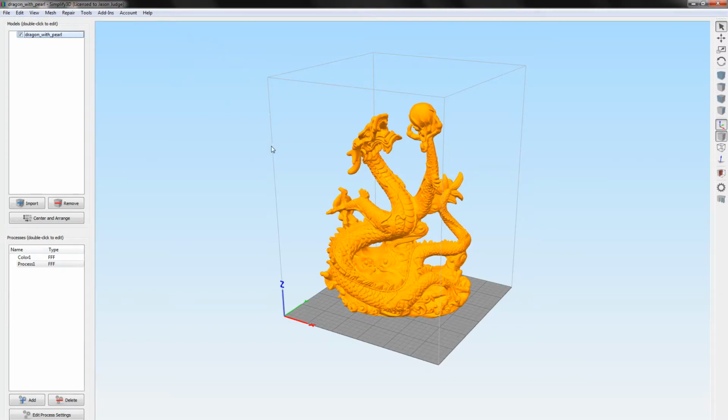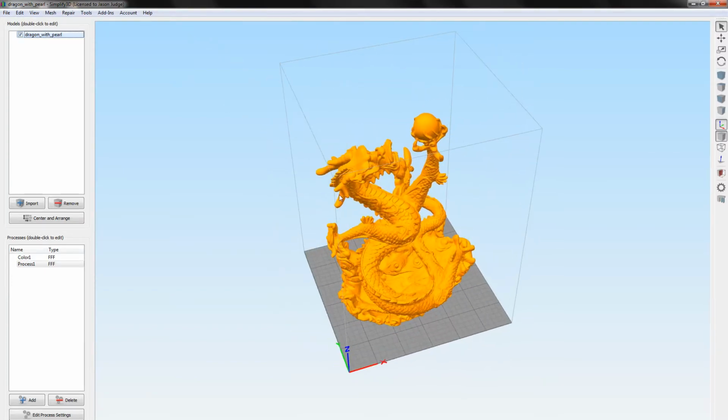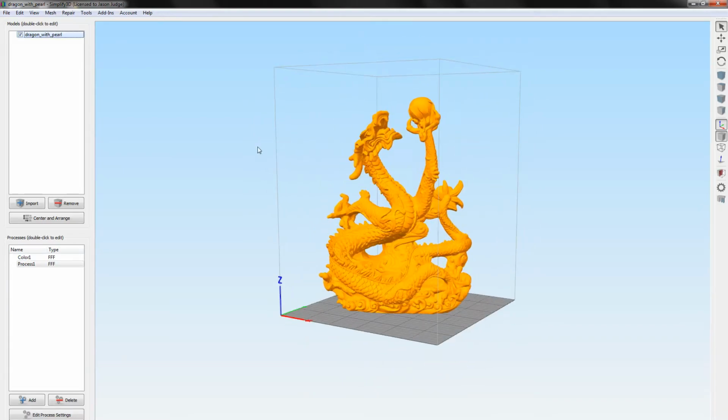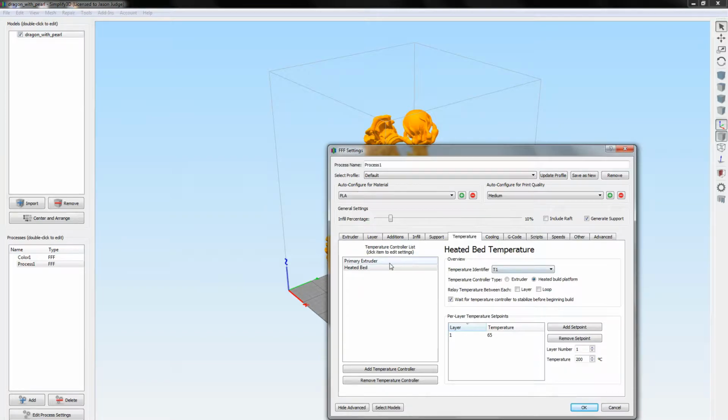So let's look a little closer at what you typically modify in the slicer for each print. Like I said, I am going to be using Simplify 3D here, but Cura also has many of the same things, although they may have some different names. So first off is nozzle and print temperature. Each spool of filament typically comes with a suggested print temperature, and you'll find that many of them say something like 190°C to 210°C or 200 to 230 or whatever. But typically, with most PLA, the ideal print temperature is going to range somewhere between 195 and 200 degrees Celsius.